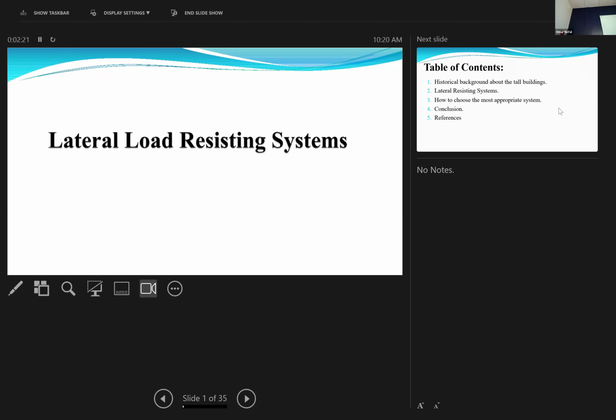But when gravity is going this way, and you have a lateral load, that means there's another system that can resist the lateral load. So if you are pushing the building this way, it doesn't matter what slab system you have. It matters a little bit, but it doesn't matter much if it's a solid slab or flat slab. They are all masses. They are all loads on the structure.